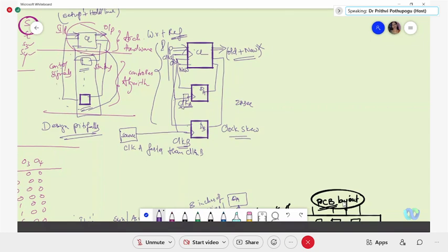That element of adding a D flip-flop or putting extra circuitry is called gating of the clock. That gating of the clock has to be avoided. Don't gate the clock. Rather, the remedy is to use a centralized source for the clock where the wiring connecting that source to all the segments will be of equal length.